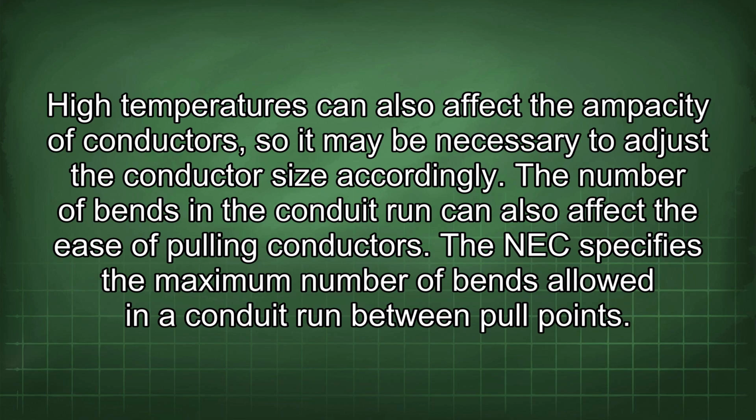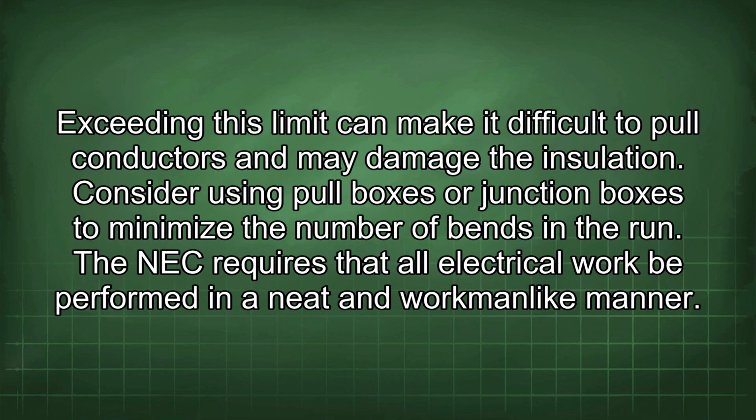The NEC specifies the maximum number of bends allowed in a conduit run between pull points. Exceeding this limit can make it difficult to pull conductors and may damage the insulation. Consider using pull boxes or junction boxes to minimize the number of bends in the run.